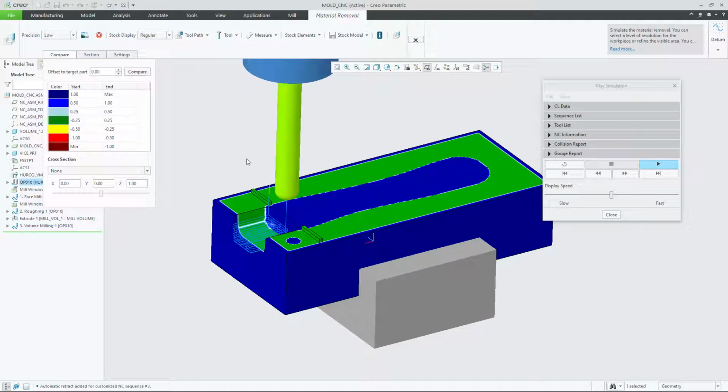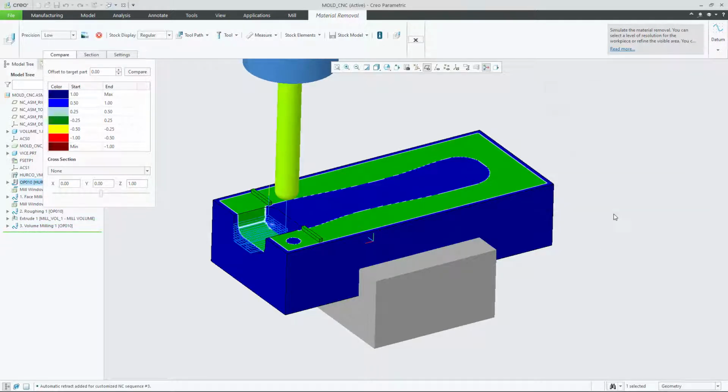The areas that I've just described as more or less finished are within a quarter millimeter, either plus or minus, of their finished shape, and the areas in blue are somewhere above 1 millimeter. So 1 millimeter to infinity is the distance that they are away from their intended finished shape and dimension. So we've got quite a lot of material still to remove.